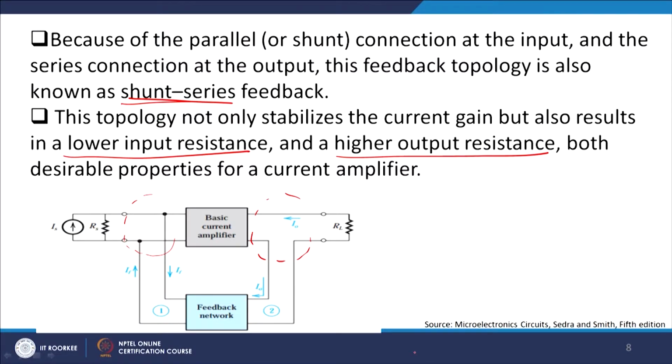And please understand that when you are discussing a shunt series amplifier, for example, you have to be very cautious that it is basically a current source which you are referring to. Now, if you remember, current source output impedance is infinitely high, and as a result, you want your output impedance to be high with feedback, because if your output impedance is high with feedback, you automatically get a much more stabilized current source, and that is the reason current series feedback helps you to achieve that phenomenon.